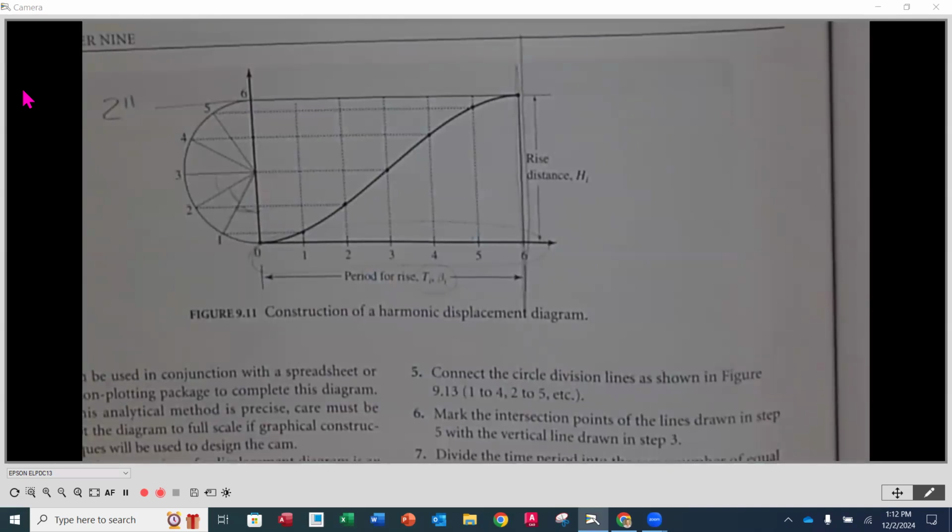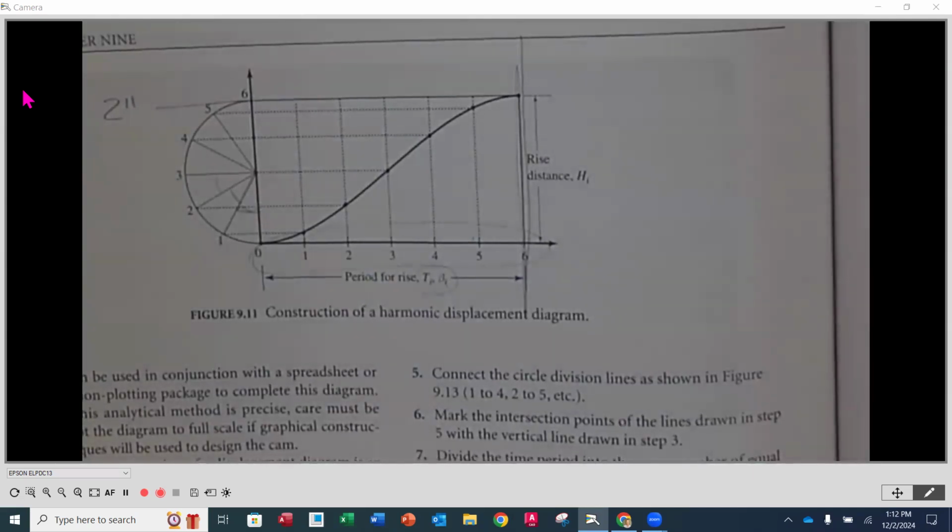They do call it a spline. Yes. So you're going to have to find where spline is in AutoCAD. If you go underneath where the line is, there's an arrow down, and then there's extras down underneath. Yeah. Polyline. Yeah, it would be a spline, Emily. Yes. But on that same order. And it's going to be a spline through points. Okay. Because you want to hit each one of those points, and then it's going to make a nice curve along that.